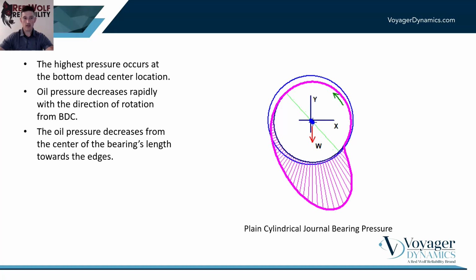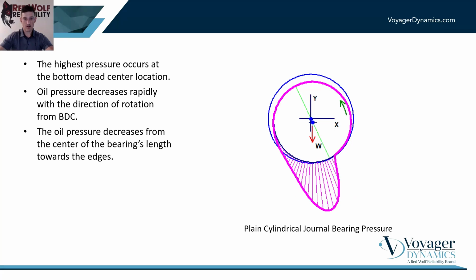And so the smaller the area that's supporting it, the higher the oil pressure has to be to support that load. Now, as we increase speed, we develop an increasing oil film thickness, and we actually spread that area out that's supporting that load, or that shaft in this case, and our oil pressure actually decreases from that startup.